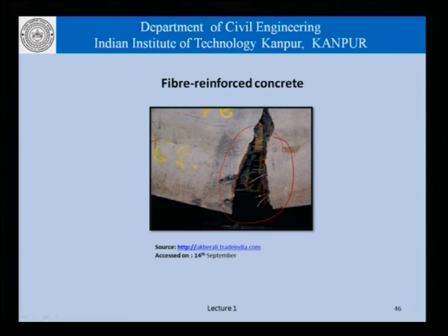Normal concrete would just fracture, but fiber concrete, because of the presence of these small fibers, does not fracture in a brittle manner. It still carries some load after the concrete has largely failed. Now, these are the ideas that are important. Where concrete has largely failed means there is perhaps a large amount of deformation which has occurred, but the concrete can still sustain at least some load.